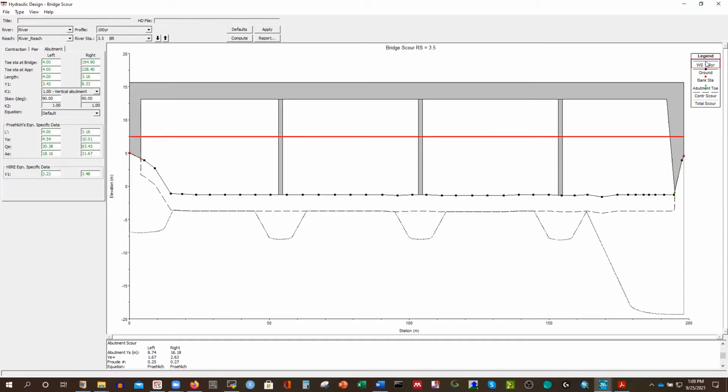That is the 100-year water level, you can see. Then this part of the bridge will be covered by water, and you'll have only this gap. If you want to pass any big ship, you'll have only this room, and you have to pass the ship within this limit. If your ship is higher than this empty space, then definitely there will be some disaster.